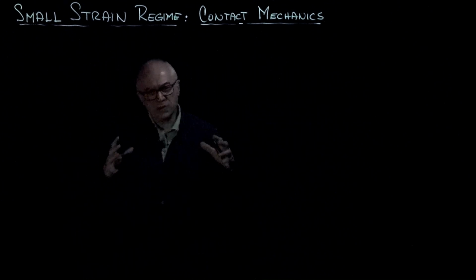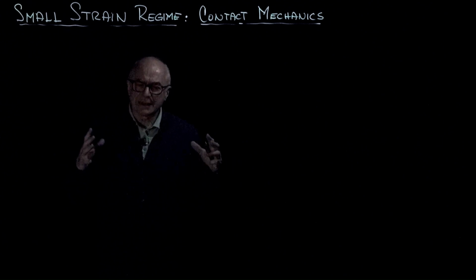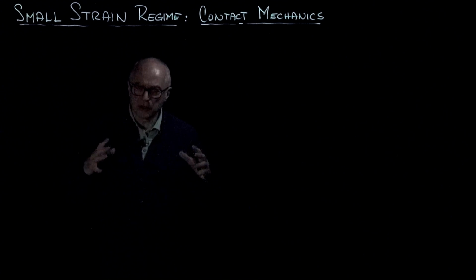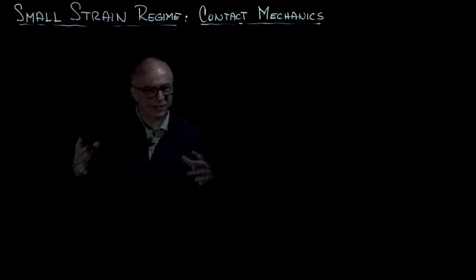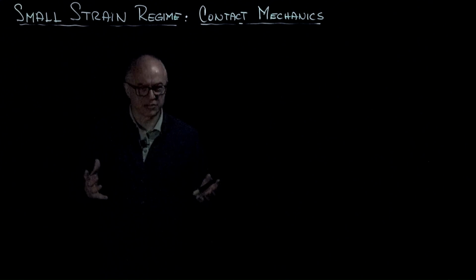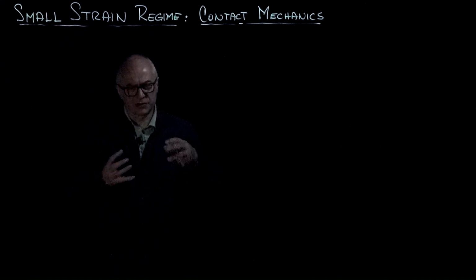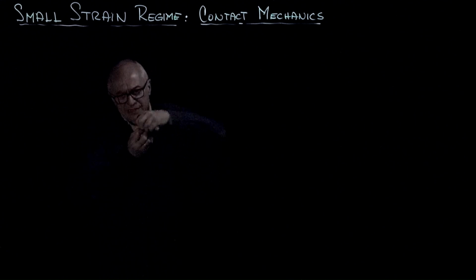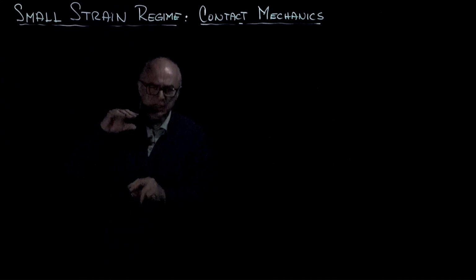When we load a granular material, a soil, under relatively low loading conditions, particles do not exchange neighbors, and there are no significant volumetric changes. However, there are deformations, and all those deformations are taking place at the contacts between particles, like when we place our foot on a soccer ball. All the deformation localizes at contacts.